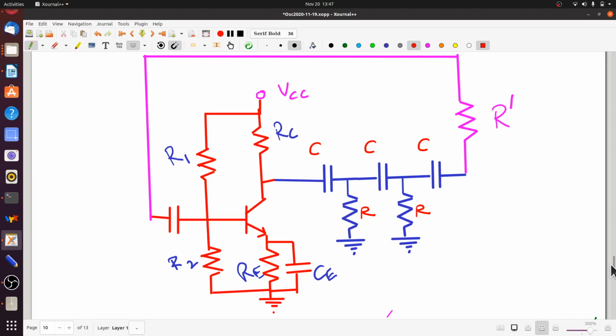Now, if you just were to analyze this circuit for high frequency behavior, the DC part of the biasing, etc., can be calculated as always. The blocking capacitors here and here, which will act like a blocking capacitor in DC, will essentially detach the feedback part completely from the circuit. The CE will be open at low frequencies, so the standard biasing calculations will work.